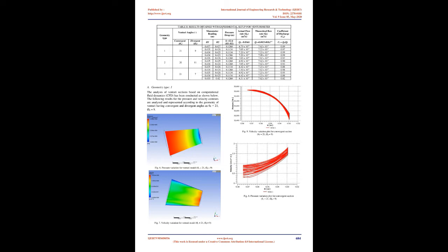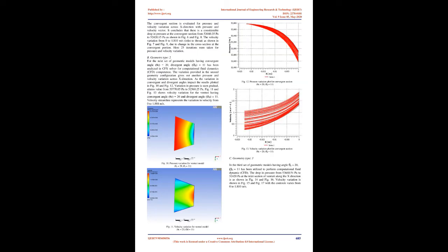This setup comprises of 2 pipelines of 40 mm and 25 mm diameter placed in parallel and fixed to the mild steel, M.S, stand. Each pipe has individual Venturi meter and Orifice meter with pressure tapings. Both Venturi and Orifice meter are fitted in the piping system with sufficiently long pipe lengths upstream of the meters. The pressure tapings are connected to a common middle chamber as well as the U-tube differential manometer. The liquid used in the manometer was mercury, specific gravity, SW, equals 13.6.